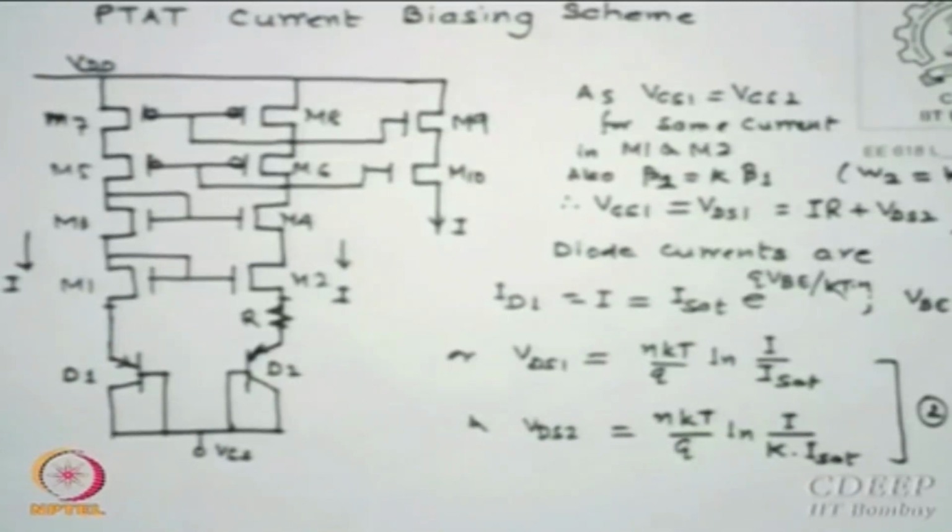And it should be independent of... Your point of view is well taken. I said this is a part of the circuit which I am going to use in the band gap reference. This does not have a good TCF anyway, is that okay? But it is not very bad either as you are thinking. You calculate that the proportionality is much better than otherwise.